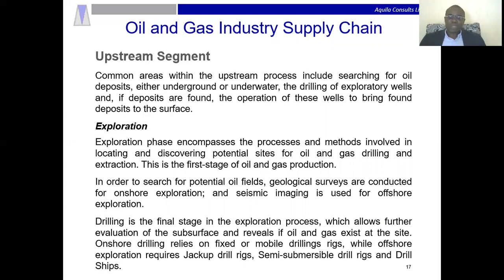After you have succeeded in doing that, you move on to drilling, which is when you actually drill the well to confirm that what you found is actually oil and gas, and if it is of commercial quantity. Drilling can be achieved both onshore and offshore. With onshore, you have either fixed or mobile drilling rigs, while offshore, you can use three types of rigs, including jackup, semi-submersible, and drill ship.